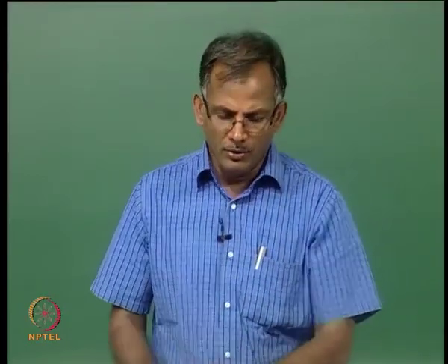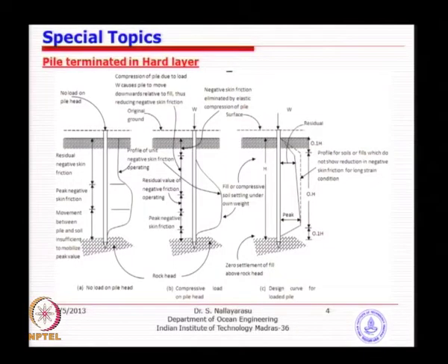For example, if you go to this picture, you will be able to understand a little easier. If you have a filled area, probably like in the cities where you have got a recent fill, and then try to install a pile foundation wherein you have slightly better stratum, few meters away or few hundred meters down. So when you try to install a pile, something like this, and you see the soil which is recently filled and has consolidation characteristics, it could be clay or it could be sand.